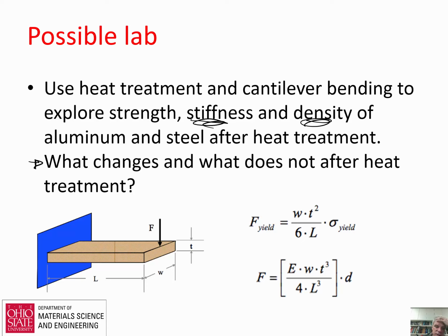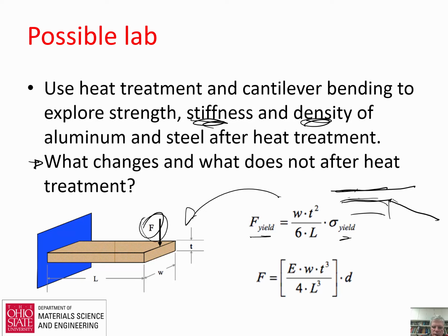the strength changes tremendously. So if we just take and basically use a C-clamp, take a cantilever beam, make a beam of the same dimension of steel and aluminum, we can measure the yield strength just by measuring the force that's required for yielding, connecting that to these dimensions. And when you get permanent deformation, meaning when you start with a nice straight beam and then it turns out where it's got a bend right where the table connects, after you remove the load, you've passed the yield strength at that point. If you just take it so the force is small enough, you're not putting permanent bending on,